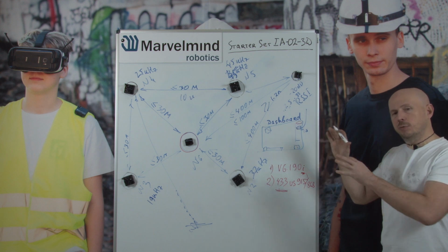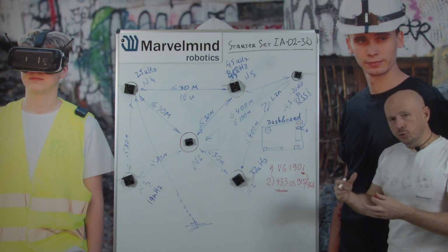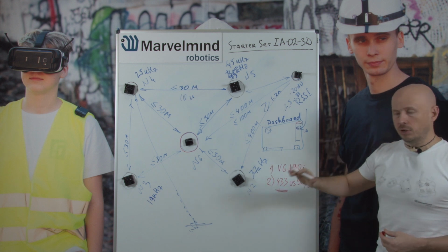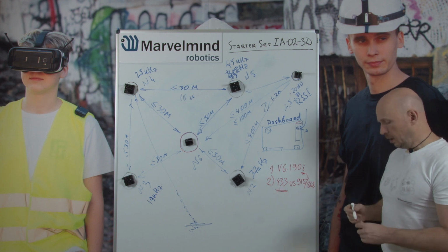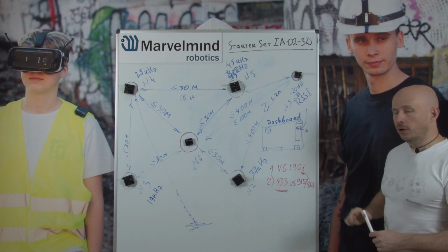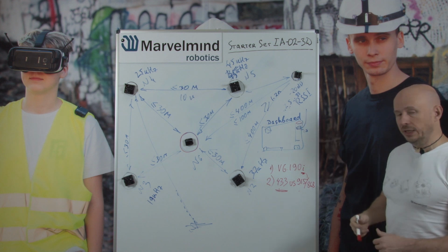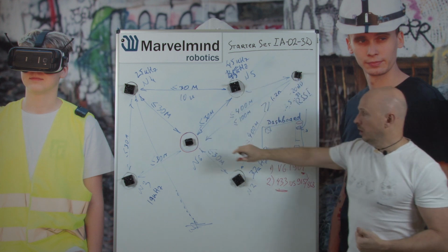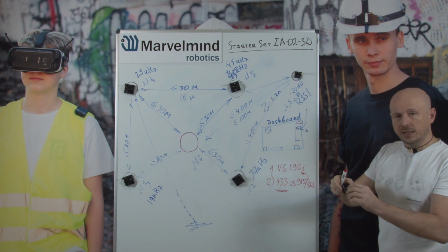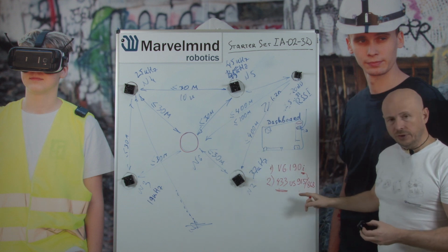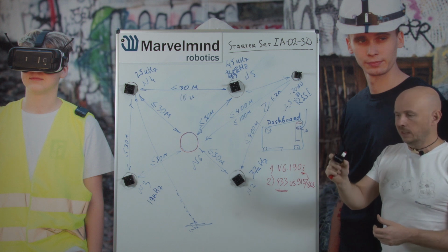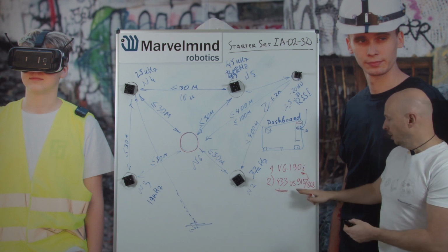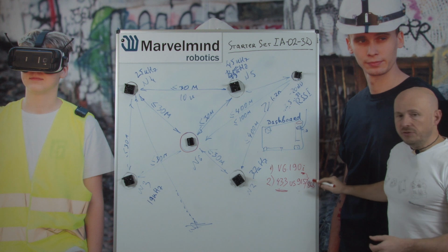Only in some very special cases, which we will talk about separately, it could be done, with some sacrifice in performance and so forth. So don't mix up. If you have the hardware for 433, you must use the 433 frequency inside your radio settings inside the dashboard. This is valid, once again, for all the stationary beacons, mobile beacons, and the modem. By the way, Mini RX has an embedded antenna, which works only in 915. So you cannot have Mini RX, at least now, with an embedded internal ceramic antenna on 433. It would be too large. So only 915.